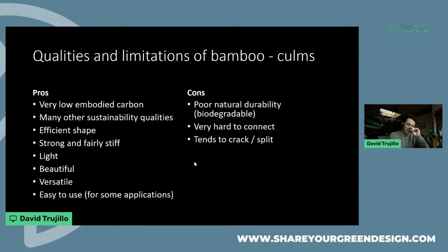And the shape also tends to be associated with a tendency to crack and split. And it is one of my greatest concerns about building with bamboo columns, this natural trend to crack and split. As engineers, the more we work with bamboo, the more we realize that this thing of connection engineering is fraught with complications. And many people who've been working with bamboo don't realize how complex this is, and sometimes they don't even appreciate that they don't know they don't know.